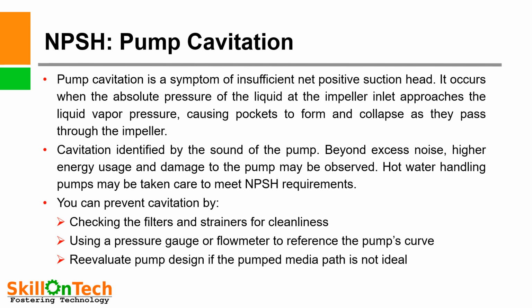Hot water handling pumps must be taken care of to meet the NPSH requirement. This is very important. When we are handling condensate or hot water, then due to temperature, the NPSH requirement may be little increased. So, a sufficient NPSH must be available over the NPSH requirement.